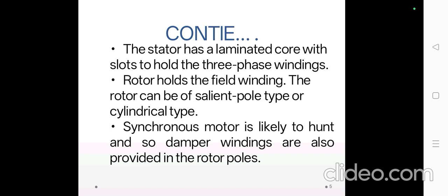The pole face has been given a specific shape. The field winding is provided on the pole shoe. These rotors have large diameters and short axial lengths. The limiting factor for the size of the rotor is the centrifugal force acting on the rotating member of the machine. As the mechanical strength of the salient type is less, this is preferred for low speed alternators ranging from 125 rpm to 500 rpm. The prime movers used to drive such rotors are generally water turbines and IC engines.